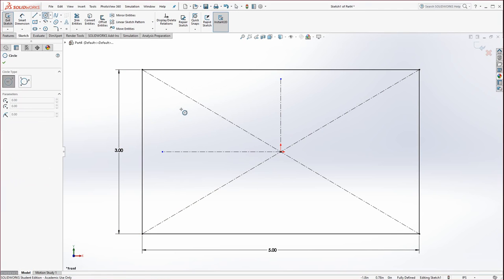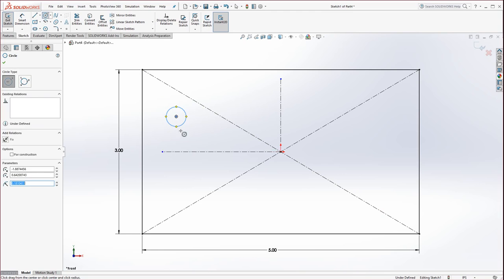With those two there now, you could go to the circle tool. Now be really careful here. Do not, and I repeat, do not touch this center line. Don't attach your circle to it, or else it's going to get stuck there. For a more advanced user, it's really easy to just delete the reference or the relation. For new users, it's not so easy. So anyway, just draw your circle floating out here. Don't touch the edge, because look at that. You're going to get tangency. Stay away from that. Click just right about here. Make sure you're not touching anything.